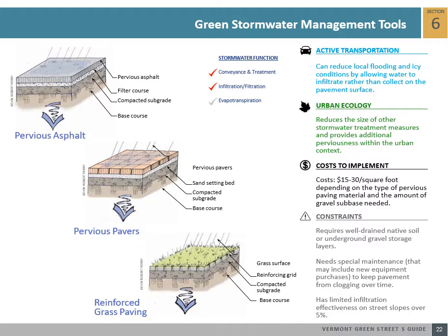Stormwater planters are easily incorporated into retrofit conditions and in places where space is limited, as they are highly versatile in shape and size. They can be built to fit between driveways, utilities, trees, and other existing site elements, and can be planted with a simple palette of sedges or rushes, or with a mixture of trees and shrubs. Because planters have no side slopes and are contained by vertical curbs, it is best to use plants that will grow at least as tall as the planter's walls to help soften the edges.